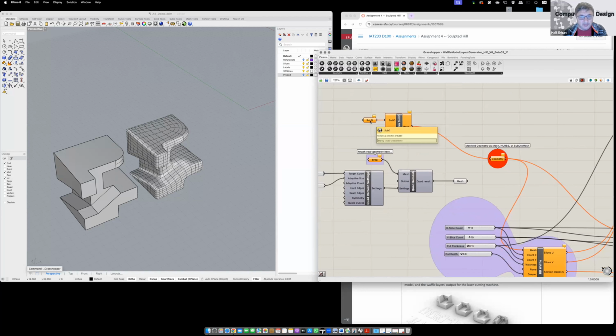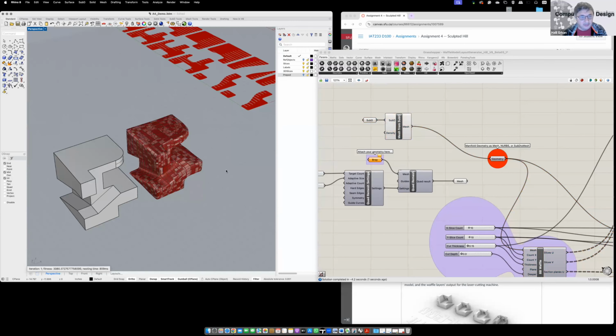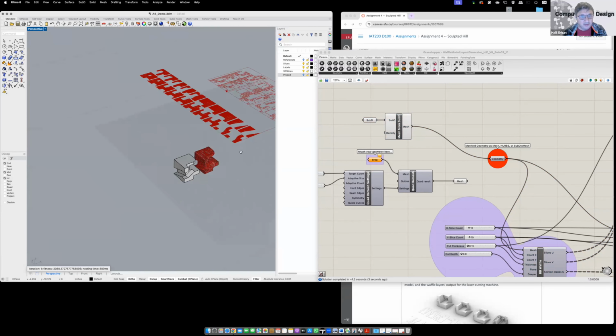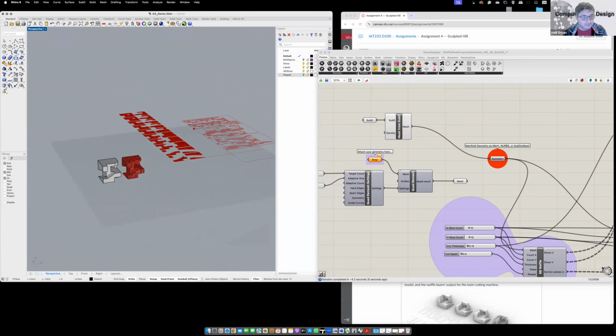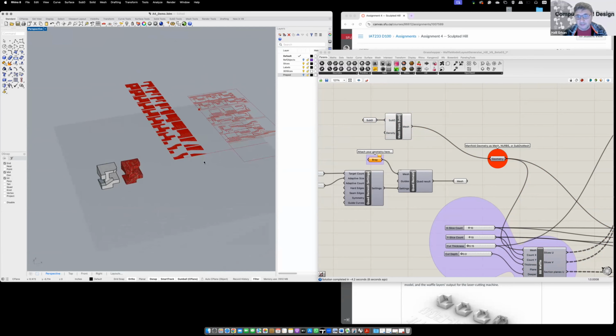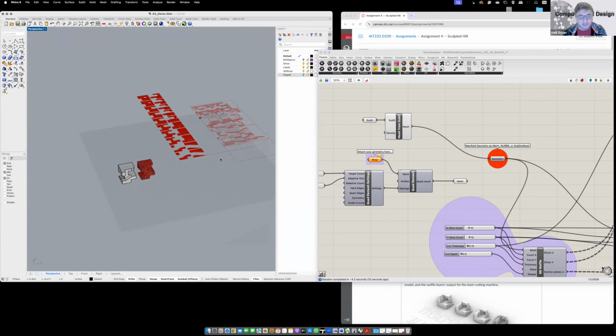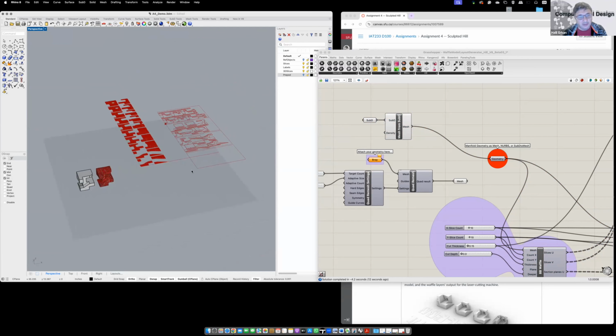I created this sub-D. I will select the sub-D, right-click, and assign my sub-D here to Grasshopper: right-click, set one sub-D. Once I select this sub-D, it crunches, of course, then it slices. It creates these layouts. Actually, I am done. From this point, it will be all cleaning up, bringing everything to Rhino and then cleaning it. What do I do next?